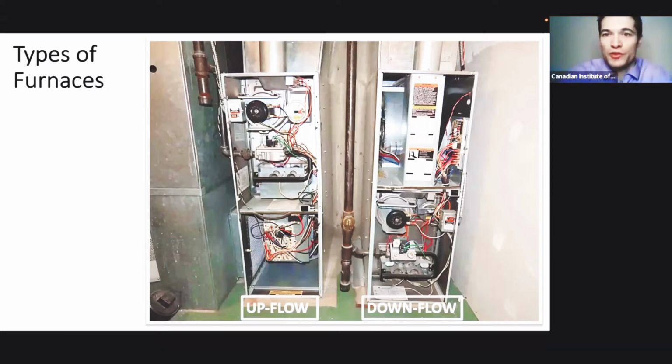A lot of home inspectors will carry around carbon monoxide detectors. They may take the detector outside, calibrate it, and then either go to the exhaust vent or go to a heat register and place the monoxide detector there just to see if there's any sort of integrity loss with the unit, primarily with the heat exchanger.